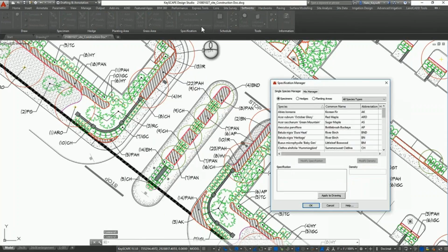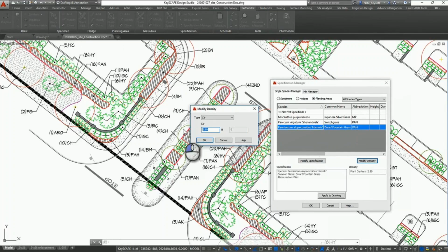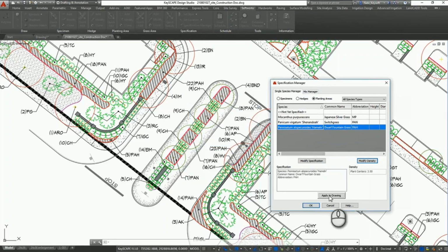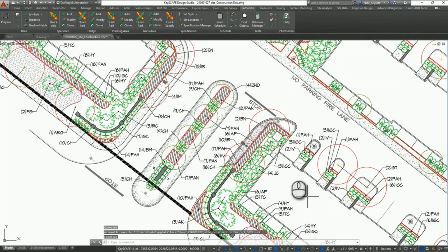And then finally, we've decided that we're spending a lot of money on these grass areas. And so what I want to do is decrease the density of our planting. This is, value engineering is always something that pops in at about this point in the project. And being able to automate some of that process can really avoid cost overruns or having to ask for additional fee. And there, every single feather grass in the project has now been reduced in density. Or you could have just done it to specific areas.